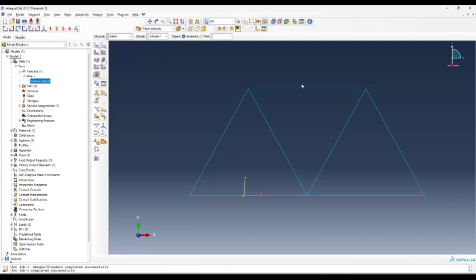And then we meshed our part. We used a special mesh for it to behave as a truss. And then we just seeded our part, assigned the special mesh type, and then we just assigned the part. And we made it so that each element was size 50. So it's basically one element per member base. Okay, so it's very easy to deal with.